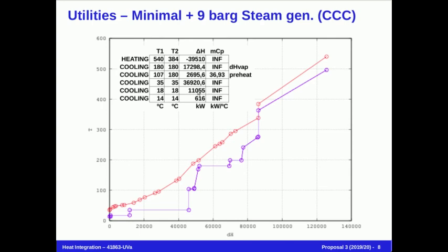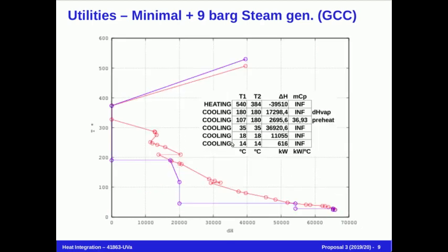These calculations have been done using the combined composite curve and trial and error. But this is more simple using the grand composite curve, as we will learn in the near future. I have also changed the temperature of the flue gases in the boiler, not the enthalpy flow, but with that final temperature we can have an idea of how much natural gas or fuel we can need.